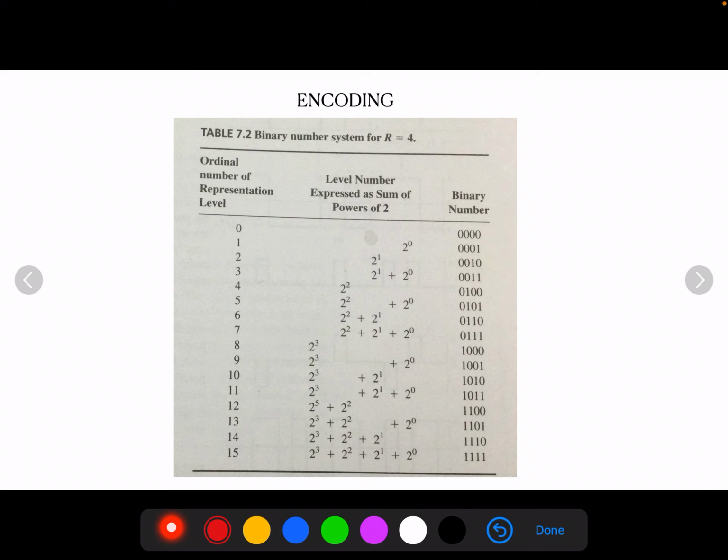In a ternary code, each symbol may be one of three distinct values or kinds, and so on for other codes. However, the maximum advantage over the effect of noise in a transmission medium is obtained by using a binary code, because a binary symbol withstands a relatively high level of noise and is easy to regenerate.